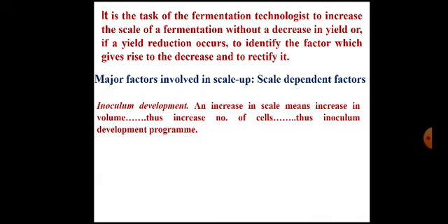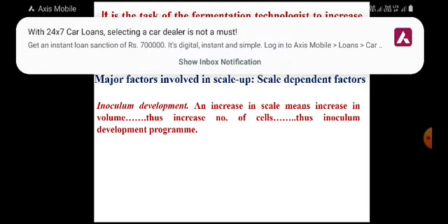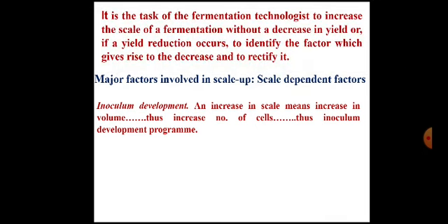Obviously, it will be higher. Therefore, inoculum size will be different for small scale, and it will be higher for higher scale. So inoculum development will be considered as a scale dependent factor because the number of cells required for the inoculation of fermentation broth is going to be increased because the volume of the medium is going to be increased.